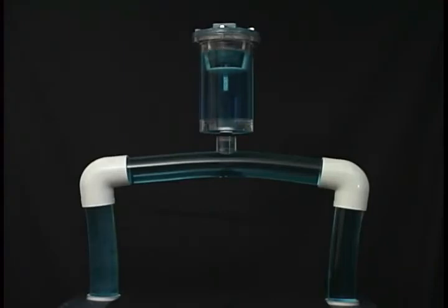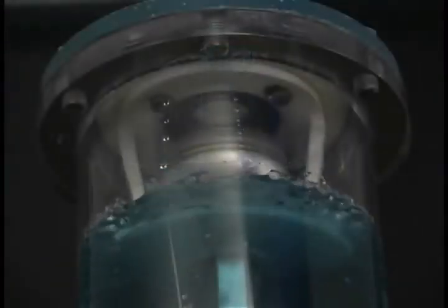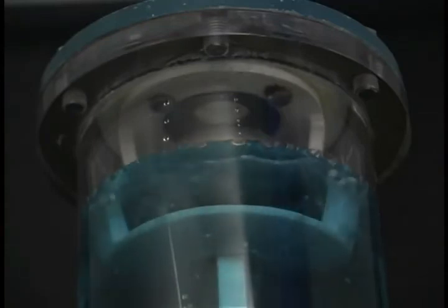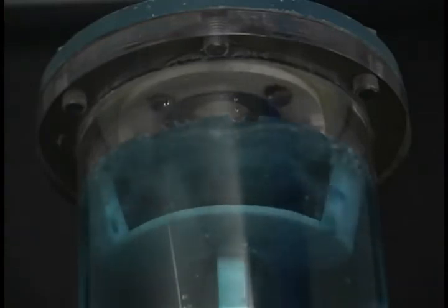As water enters the valve, the float will rise, closing the discharge port. The valve will remain closed until system pressure drops to near 0 psi. It will not open and release any accumulation of air while the system is under pressure. A close-up shows the water entering the valve, raising the float into the resilient seat and closing the valve. The float and float stem are guided by a hexagonal float guide. This assures positive seating of the float and protects it from colliding against the interior of the valve.